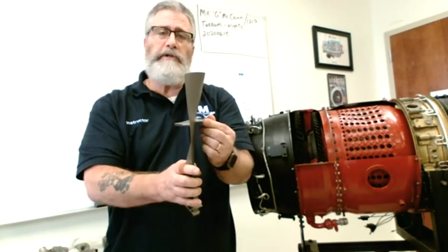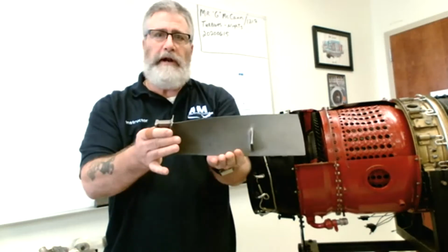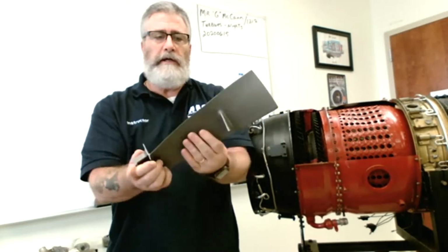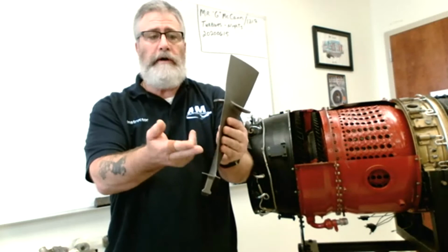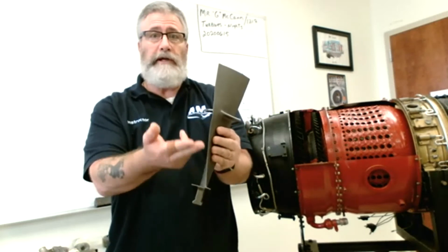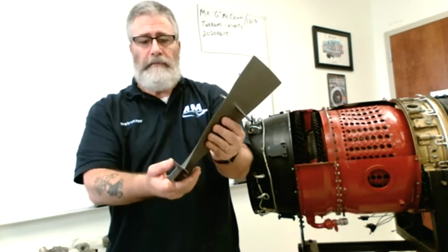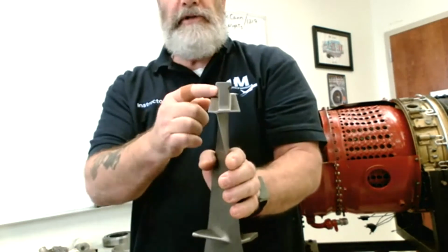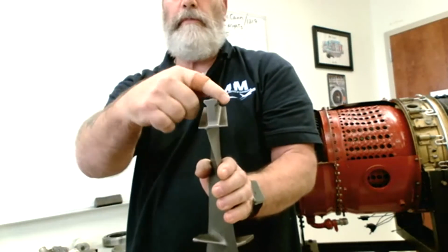So we have a lot of words to remember, but mid-span shroud, because remember, this is nothing more than an airfoil, right? So we have a span, and we have a chord, all right? So even though it's not exactly in the middle, or there might even be more than one, they're all referred to as a mid-span shroud, okay? Remember that. Now, on the mounting side here, now that I get into this, there's different ways to mount blades, whether it's turbine blades, fan blades, or compressor blades, right?